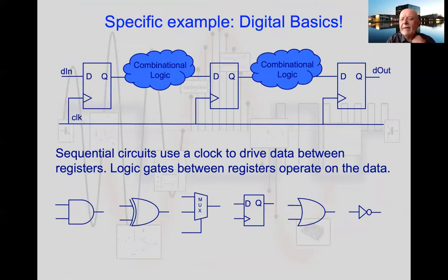Okay, so let's now talk a bit more about digital. As I've said here, some basics of digital design. Almost all digital design you can reduce down to this very basic circuit, where we've got some sequential logic, or in this case registers or D-type flip-flops, but let's think of them as registers, which are clocked to drive data between the different registers.